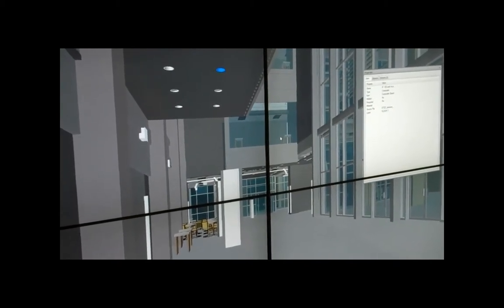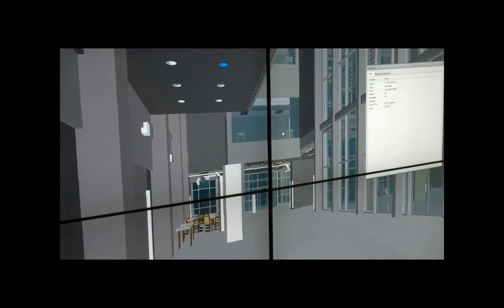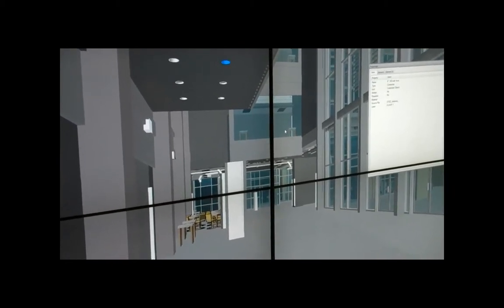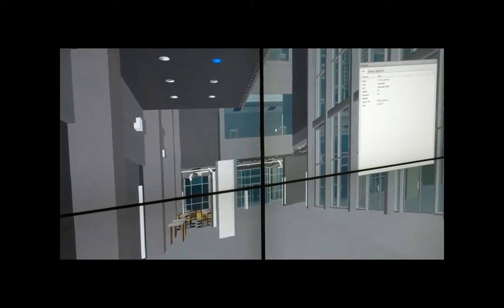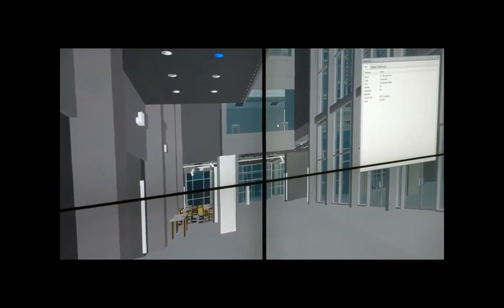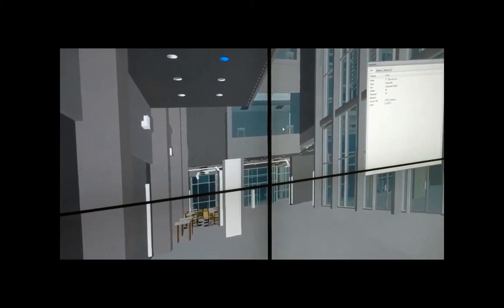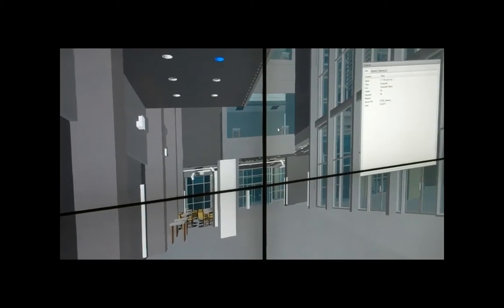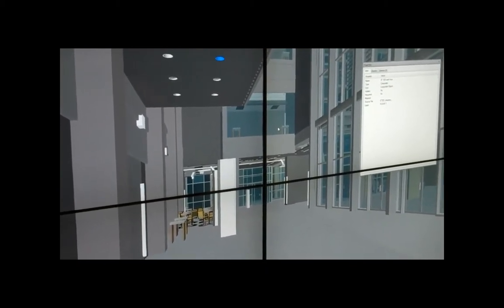So a very detailed 3D model is the one that we use in construction, especially for pre-construction coordination meetings. We use the model of the architecture, structure, and MEP so that we make sure there will not be any clashes between those objects before we start working on the construction job site. In usual cases, you will see lots of clashes between the components before you start construction.